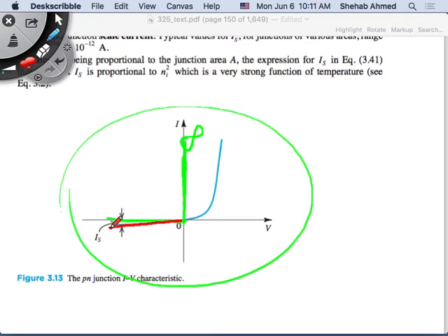As soon as I put a reverse voltage and I'm increasing this barrier potential, I'm helping the minority charges pass through, and this is sort of increasing linearly. So, it's probably a dumb question, but is IS the saturation current? There's no dumb question. Yes. It's when the minority charges are drifting. Right? It's minority charges drifting. So that's why it's limited, because it's due to the minority charges.